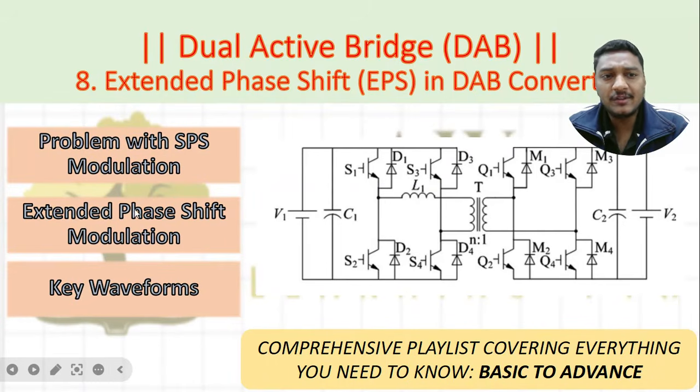Then we will touch upon the extended phase shift modulation and see the key waveforms associated with it. This is very important: whatever problem we see in the single phase shift modulation can be eliminated with the help of extended phase shift modulation. And how the different waveforms look in the extended phase shift modulation, we are going to discuss in this video.